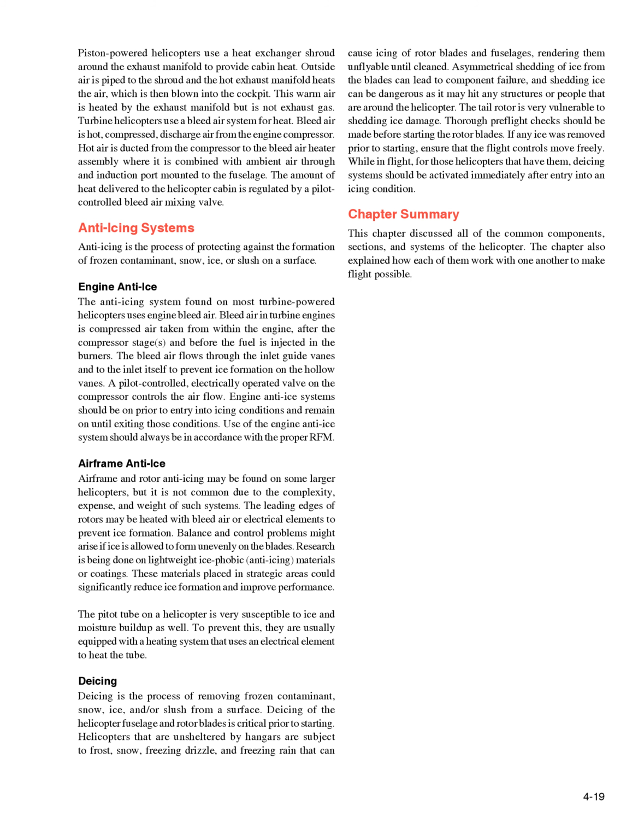Anti-icing systems. Anti-icing is the process of protecting against the formation of frozen contaminant, snow, ice, or slush on a surface. Engine anti-ice. The anti-icing system found on most turbine-powered helicopters uses engine bleed air. Bleed air in turbine engines is compressed air taken from within the engine, after the compressor stages and before the fuel is injected in the burners.